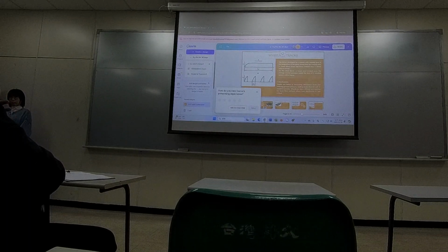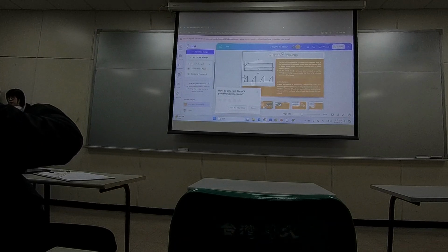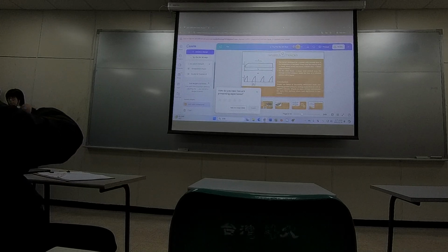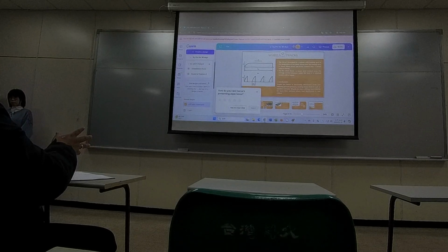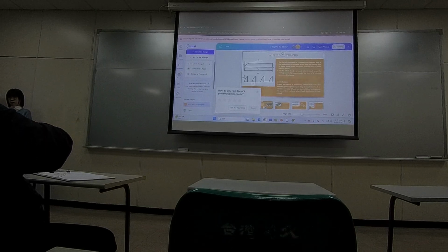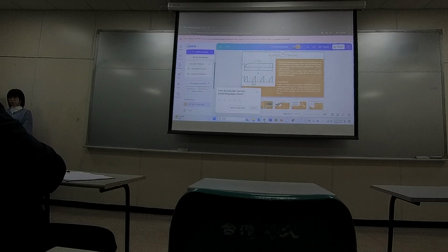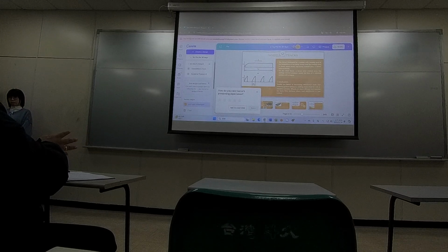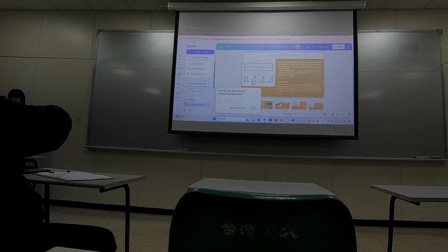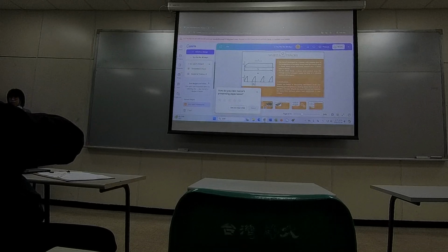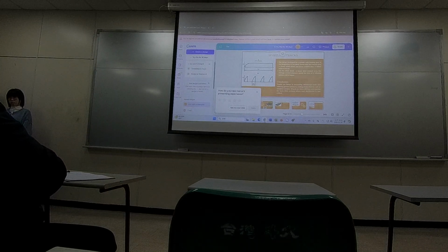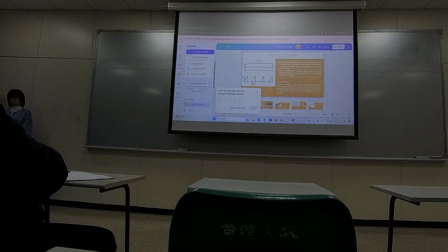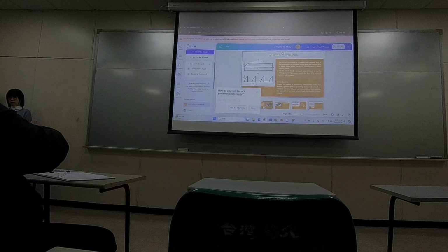But the problem here is the weight which is in the center. In the center of the chassis we have 4 wheels to support. To avoid the buckling, we have 4 small wheels, and that is creating the floor damage, not the Magnum wheels. Yes. So this track will replace those 4 wheels, which are in the bottom middle. So the problem is not the Magnum wheels. Yes. The problem is the small wheels in the middle which support the frame. Those wheels are creating the floor damage, not the Magnum wheels. Magnum wheels are okay. Yes. So how can this track avoid it? It can eliminate the 4 wheels.